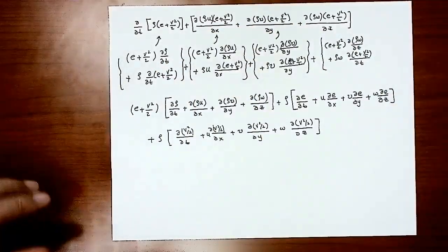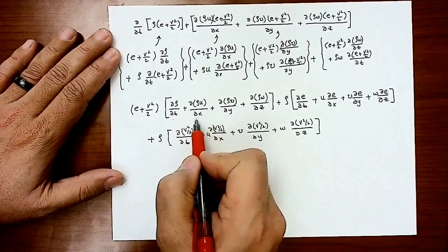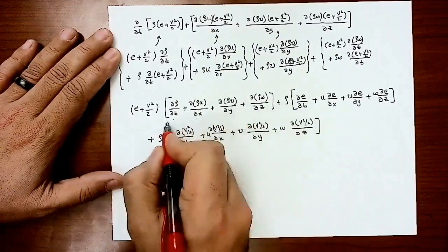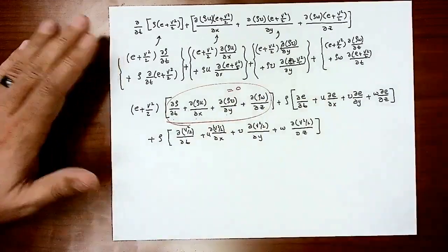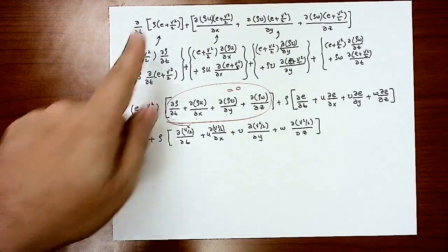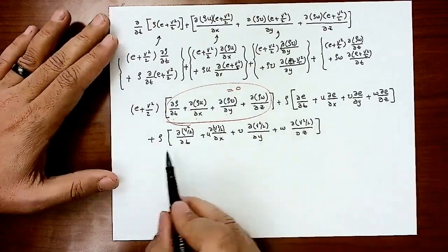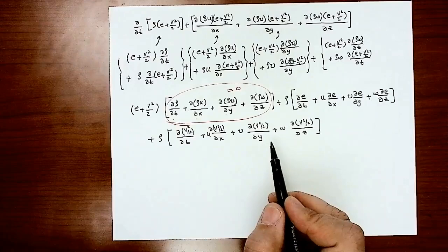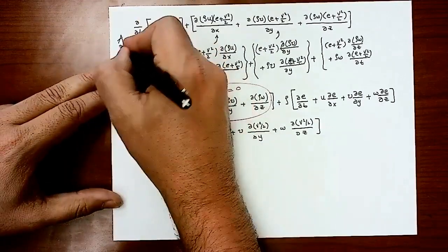Let's see now. What is this? ∂ρ/∂t plus ∂(ρU)/∂X, same for V and W. This is the continuity equation. So this is actually equal to 0. This term is gone. So I get rid of this one. So these two terms end up being this one and this one as well. So that's the remaining of that part. Let's call that step A.